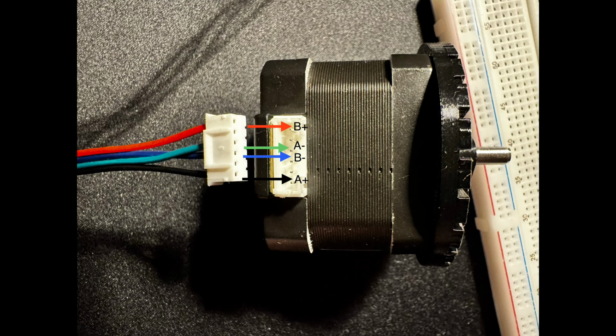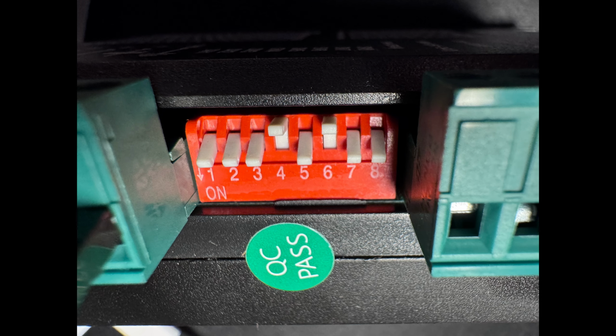The DM driver has DIP switches on the side. Some switches configure the motor current, other switches configure the microstepping mode, or pulses per revolution. The current table is used to match the driver output current to the motor current rating. The pulse per revolution table defines how many step pulses are needed for one full revolution. For example, with a 1.8 degree motor, 200 pulses for full step, 400 pulses for half step, and so on.